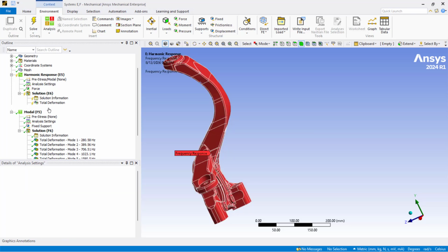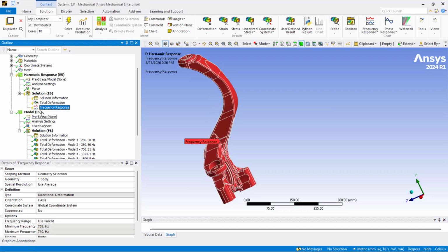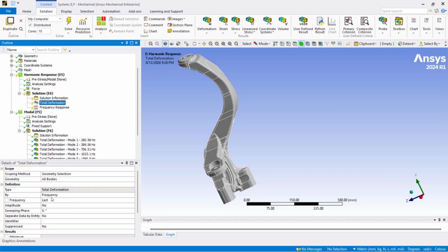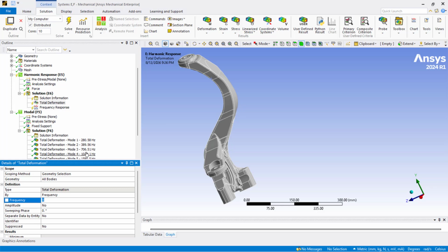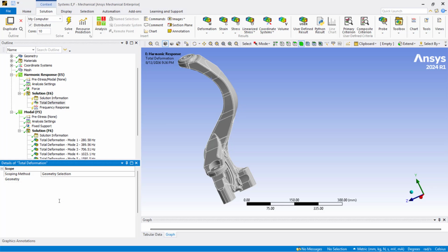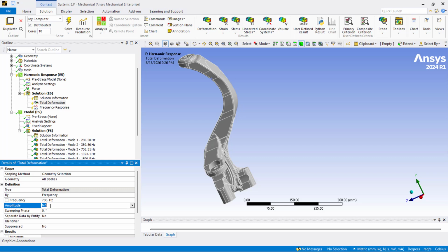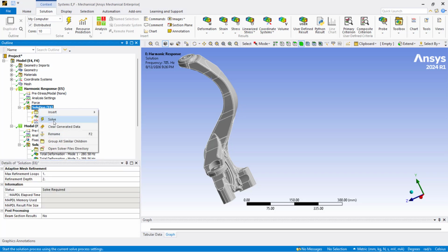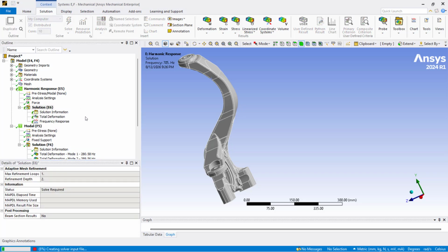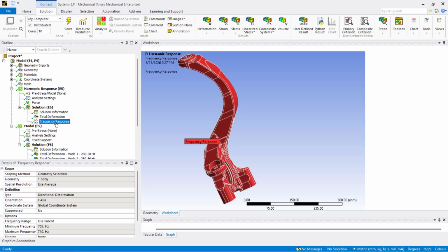I think all are fine. So what we checked, only the damping there is fine. Here deformation should be exactly on 706. Let us see. And amplitude I need to cross verify, not needed now. So let us run this. Okay, solve. Now we are only concerned about the frequency response. At that peak, it should be less than 2.6 mm is what our expectation is.